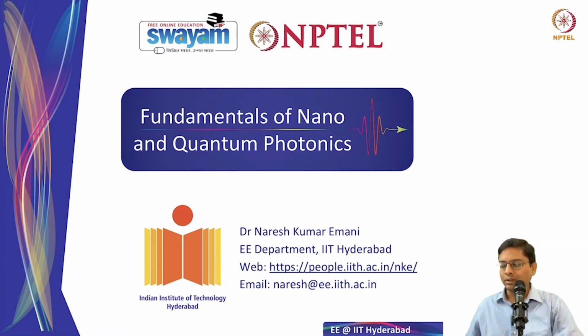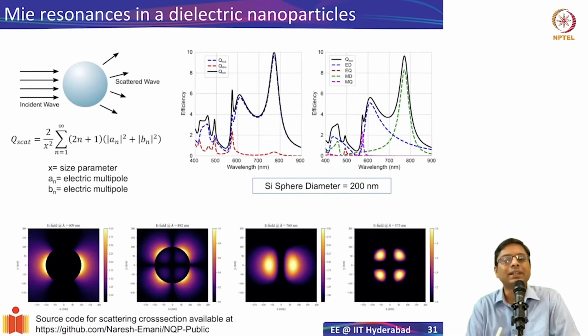But plasmonic metasurfaces also suffer from one drawback. That is the inherent loss in the metal. We have seen that we choose either silver or gold because they exhibit extremely low loss. But even then, that can be significant in some applications. In that kind of a scenario, it turns out that dielectric nanoparticles or dielectric nanostructures are useful. The reason is we can try to engineer the response in such a way that the dielectric structures have extremely low loss, and they can be useful.